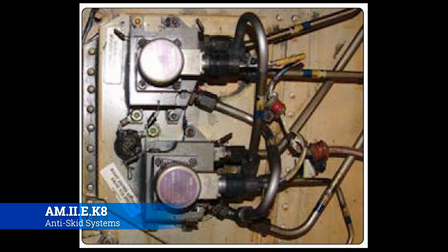Now, these will tie directly into the other brake lines, or the brake system, and be just a part of it. For the most part, they don't do anything. They basically stay in their fixed position, and they only ever actuate under very strict conditions. So typically, the part that goes bad with an anti-skid system is going to be your wheels, because they're down there with the muck and the grime, and they also are electric, and being down there in those types of conditions is generally not the best thing. They also have the most kinetic use, so they spin the most.